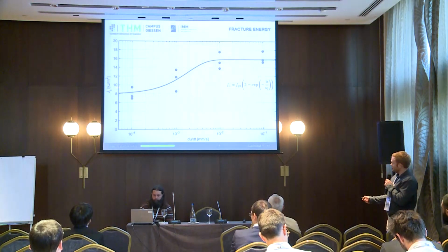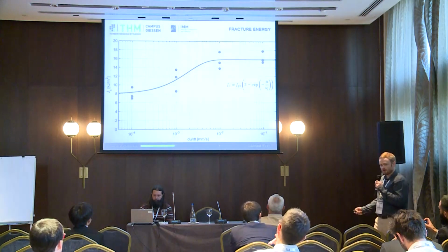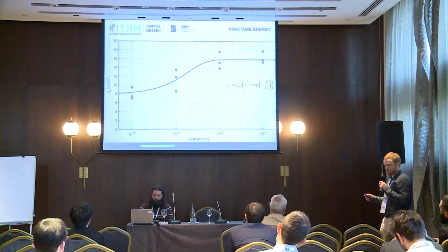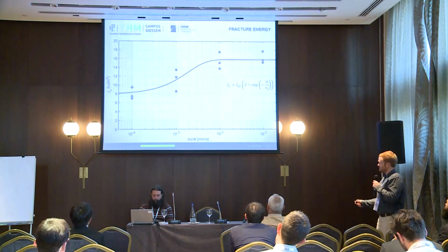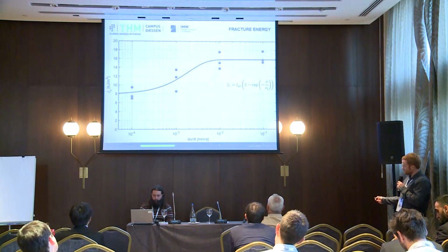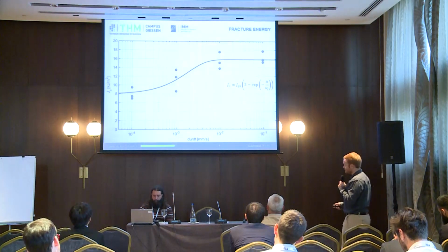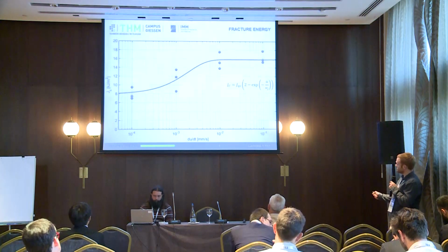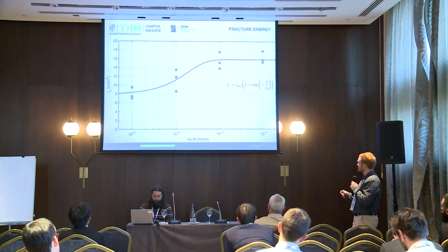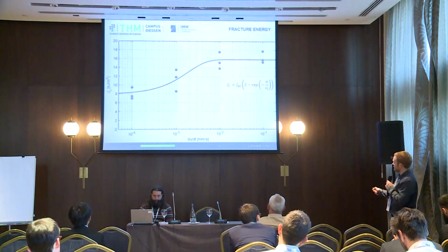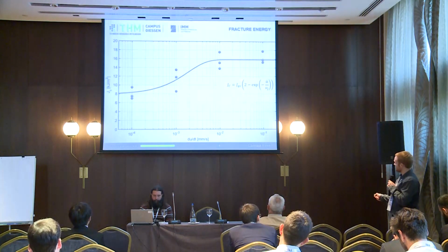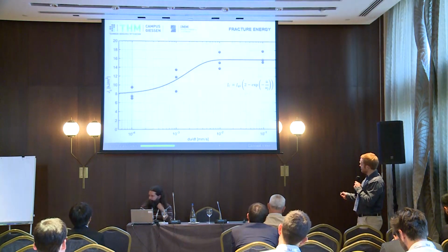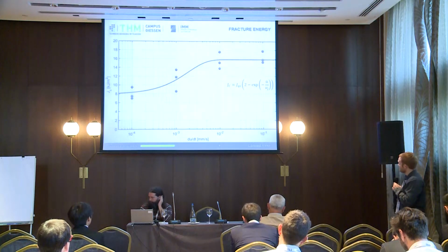This approach has a lower bound here, which is physically sensible if you think that fracture energy must not fall below 0 for the quasi-static limit case. But we can say this plateau is not really convincing, but we've chosen to think about this plateau as sensible. And we've seen a plateau for higher rates. So J quasi-static is the lower plateau, and this is a fitting parameter where this curve here changes its curvature.